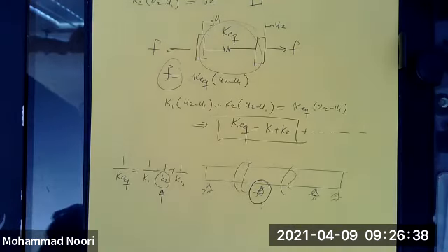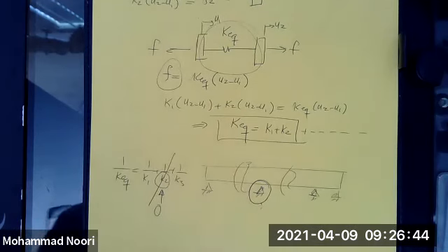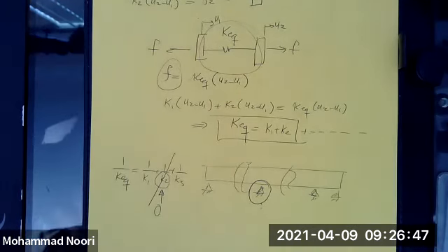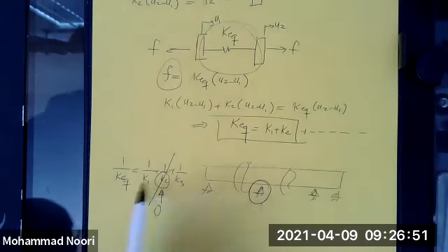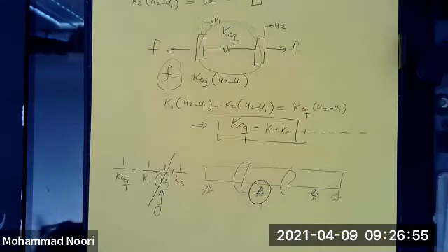Let's say you would increase that stiffness to infinity, right? What happens? Contribution would be zero. So by stiffening that component, given that these bearings are all in series, you have actually made the problem worse.